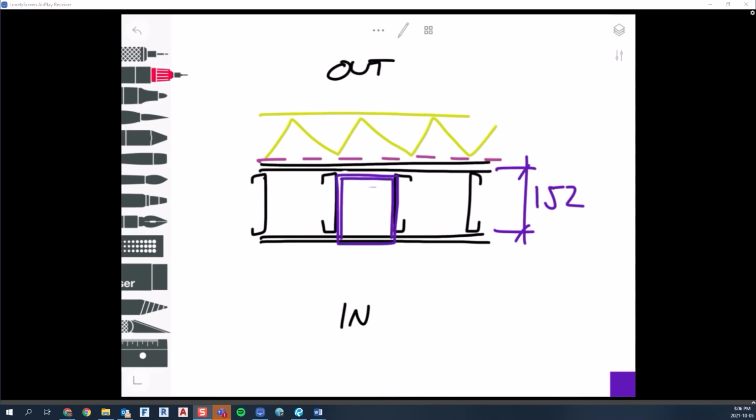Or whatever. And then, of course, you'd have to fur around that. It'd be a little bit more than that, I guess, but you'd fur around that with gypsum board, however you need, and you end up with a bump in the wall. Maybe that's okay, maybe not. It's a design choice. So, when you're doing the infill stud, I'd say the intent there would be to bury that column.